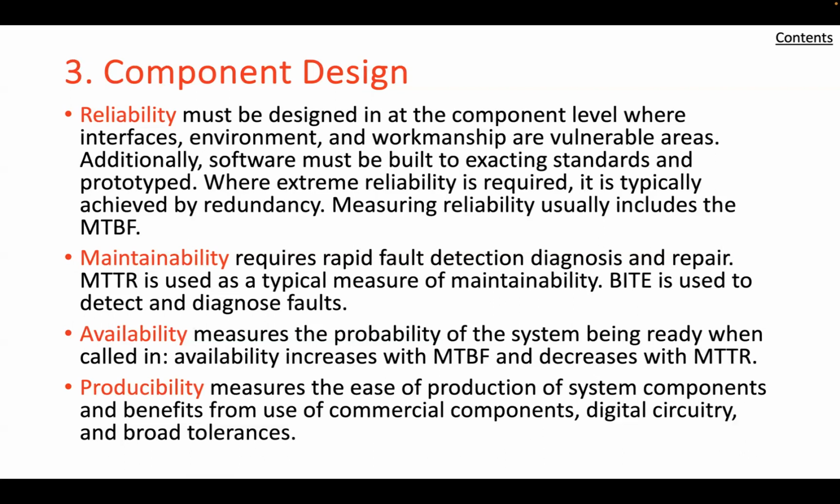Since to repair a system failure it is first necessary to identify the location and nature of the fault, that is, to carry out a failure diagnosis, system design should provide for means to make diagnosis easy and quick. In case repair is needed, the design must be dovetailed with logistic support plans to ensure that the components or component parts that may fail will be stocked and be replaceable in minimal time.